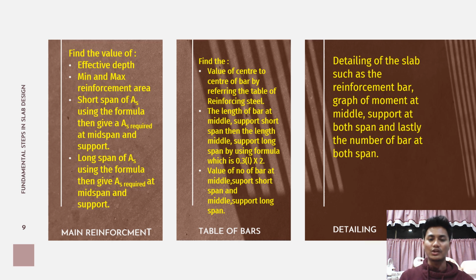And lastly, you should sketch or draw a detailing of the slab, such as reinforcement bar, graph of moment, and the middle and support at both spans, which is short and long span, and lastly the number of bars at both spans.